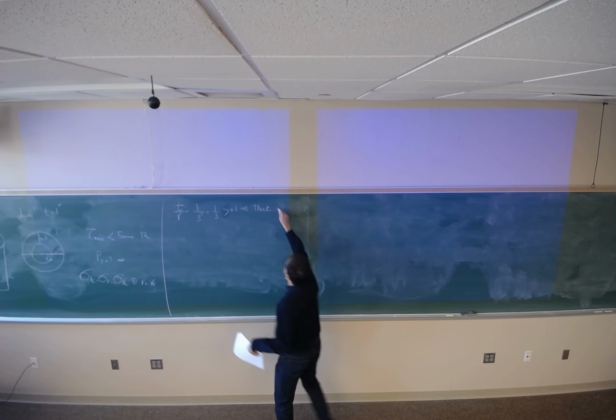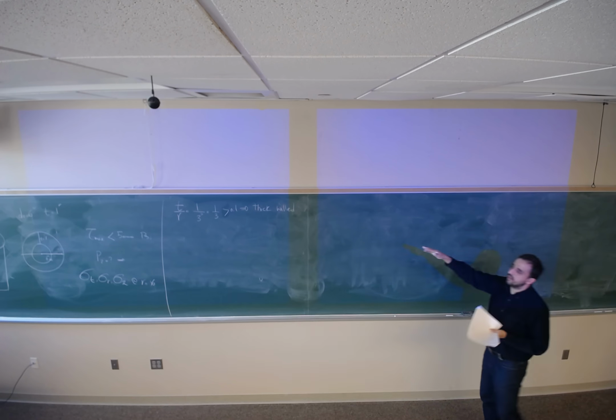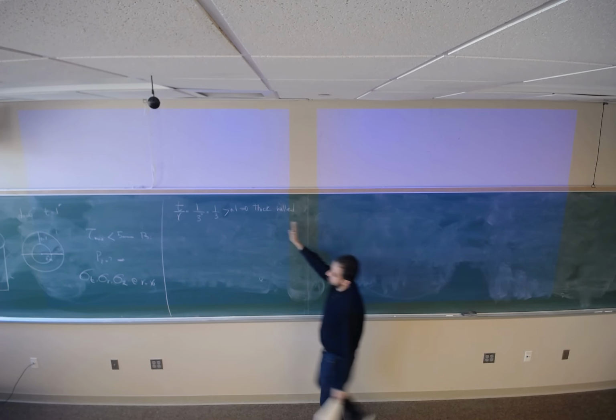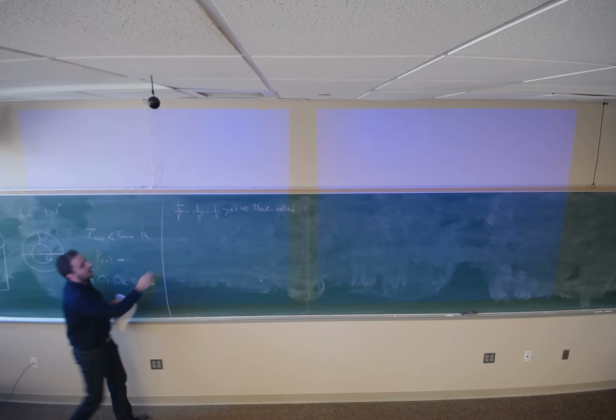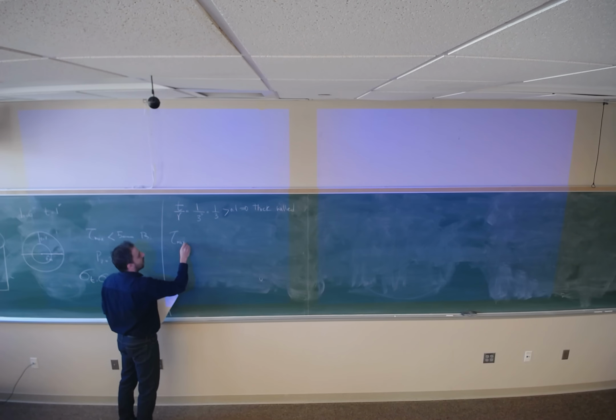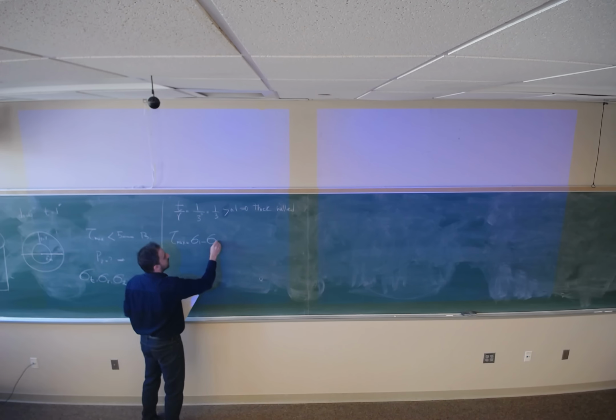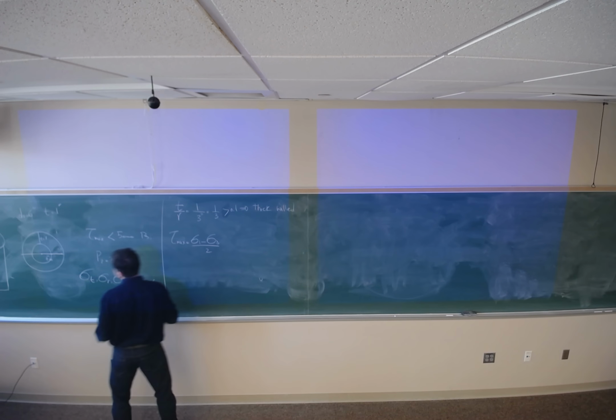Thick vessel. So you cannot start the process before checking this, because you don't know which equation should be used. So tau max always is sigma 1 minus sigma 3 divided by 2.